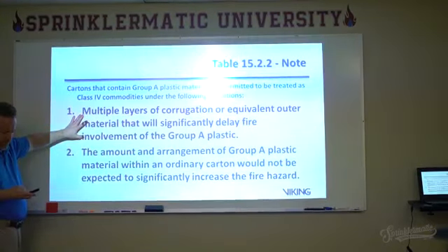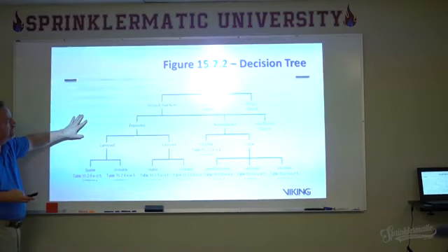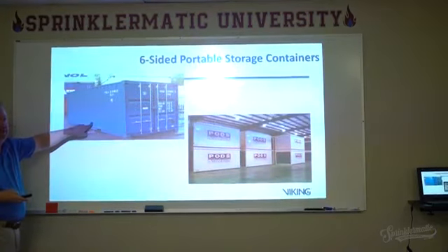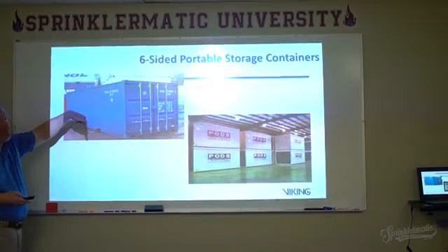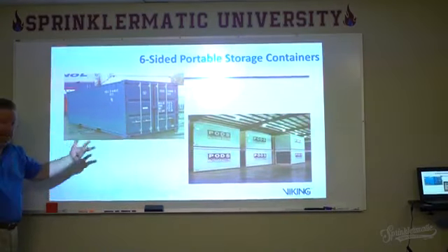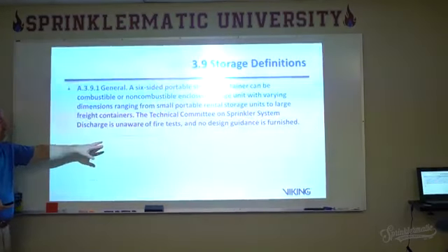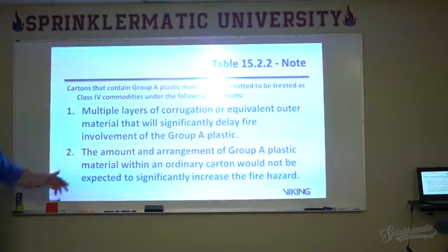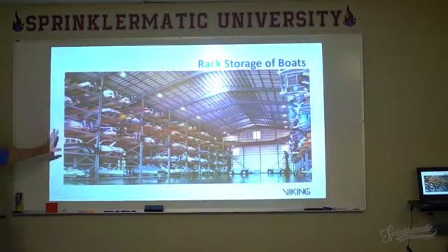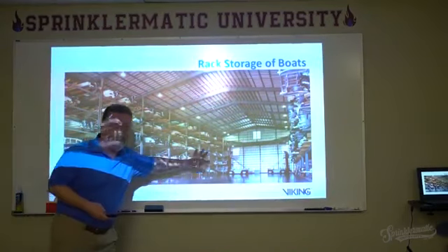Because this thing kind of looks better than a cardboard carton, doesn't it? Like it would resist fire in a cardboard carton a little bit better. We're not talking about dropping protection down into it. We're just talking about protecting the warehouse that it's sitting in. So it's possible. I tell you that mainly because when I asked the question, some people said, no, you can do it as a Class 4 commodity, and others said, no, we just do ESFR Group A plastics and we're done with it.